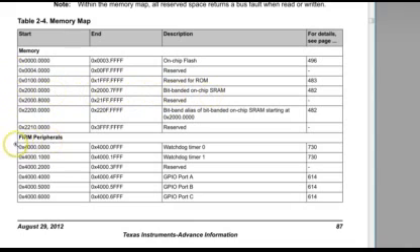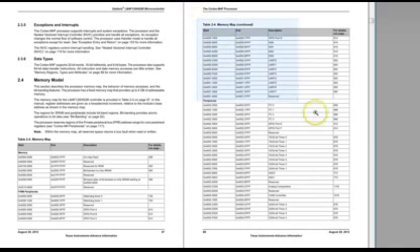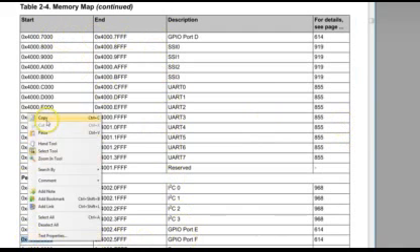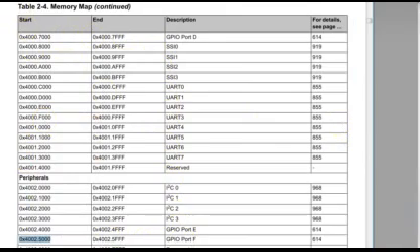In the peripherals continent, you should note the GPIO ports. These islands are interesting because you are looking for GPIO port F to control your LED. Keep looking further down the memory map. Hey, here is GPIO port F that you've been looking for. Copy the starting address to the clipboard and go back to the IAR debugger.